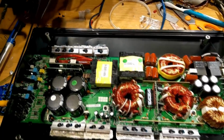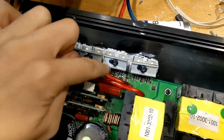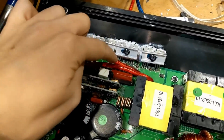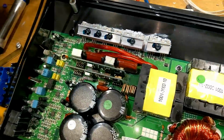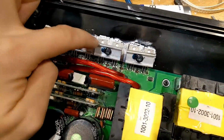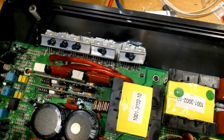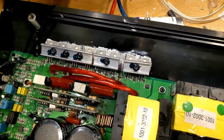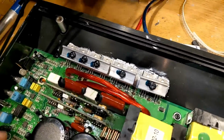Yo, so here she is. Replaced these bars with these solid DD cables. They won't vibrate out again, and they actually have a slightly lower resistance than these bars, so that's a positive. All 8 of these output MOSFETs have been replaced with 61N20Ds, which are much higher current, lower RDS MOSFETs, which is going to be running cooler, a bit better, more reliable operation.